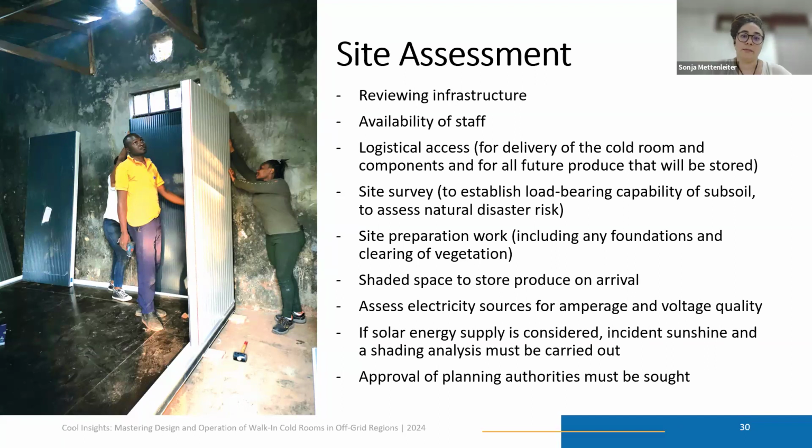And then I mentioned the rainy season. A site survey is very essential to establish the load-bearing capability of the subsoil. So can the subsoil support the cold room? And also, what are the risks of natural disasters? So we had the example of Kenya. Here in Kenya, we had really heavy rainfalls in the last month, and that led to some flooding. So that should be assessed beforehand. How safe is that location against those climate risks, but also risks like earthquakes?